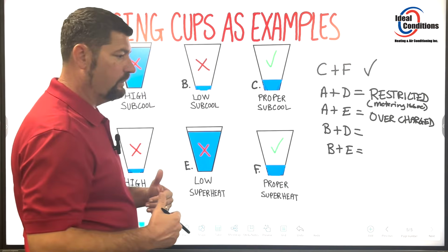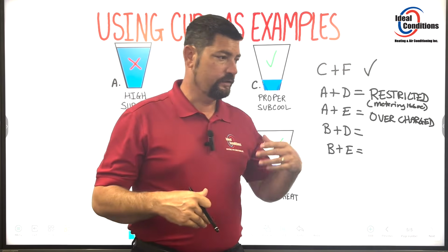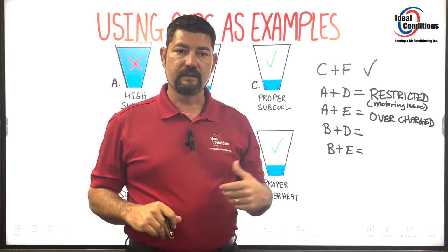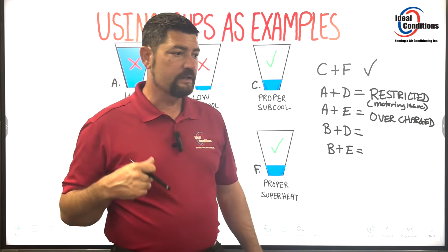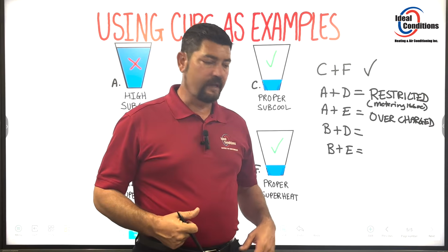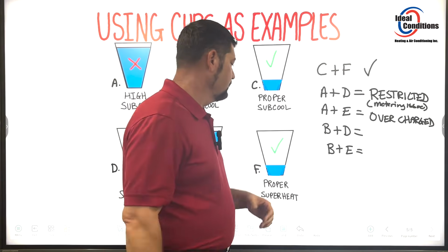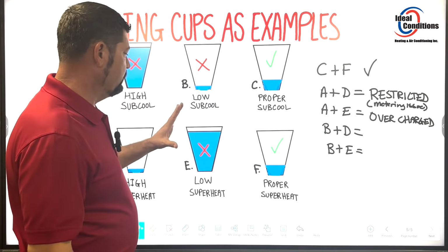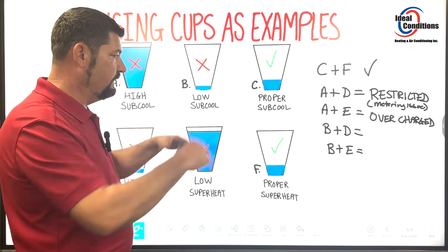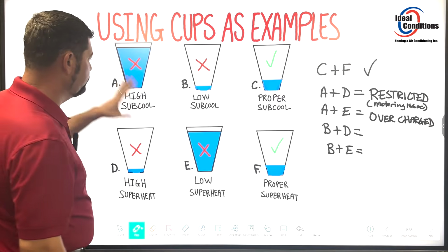Because when you're looking at your manifold, you're looking at pressures, suction pressure and head pressure. You're looking at liquid line temperatures and suction line temperatures, and vapor saturations and liquid saturations. And you're looking at the superheat values and the subcool values. And all of those values are going to spit out a combination that you're supposed to understand what those numbers mean. And we're only taking a couple of values. We don't need the high pressure and the low pressure, right?